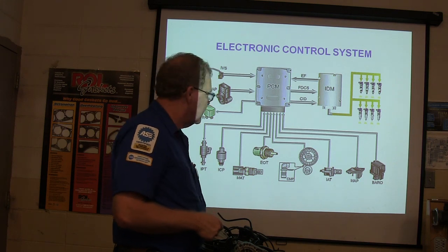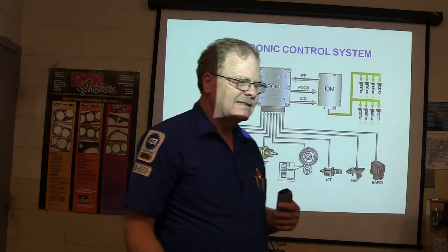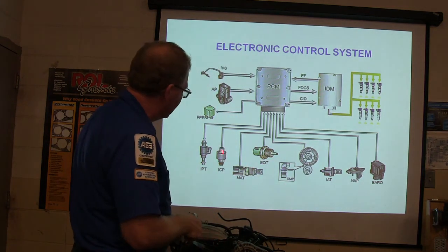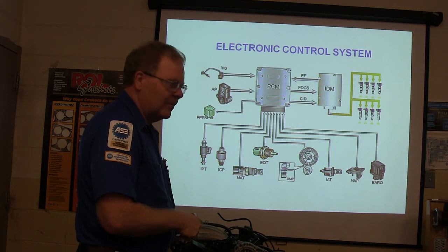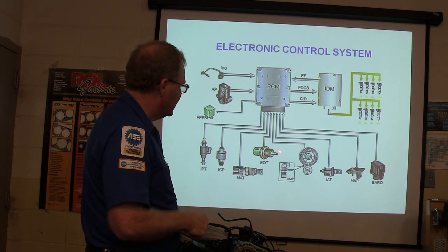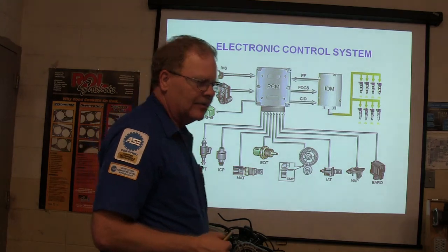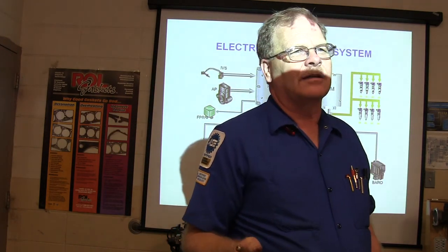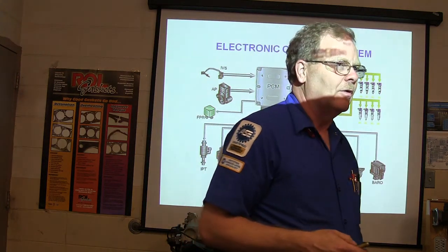Oil pressure. Well, you don't necessarily need to have that. Oh, well, you actually got an injector control pressure sensor, but as far as engine oil pressure, no, they don't have that. But what you're also missing, this is engine oil temperature, but you don't see engine coolant temperature on here. It couldn't care less about the temperature of the coolant, it's more concerned about the temperature of the oil.